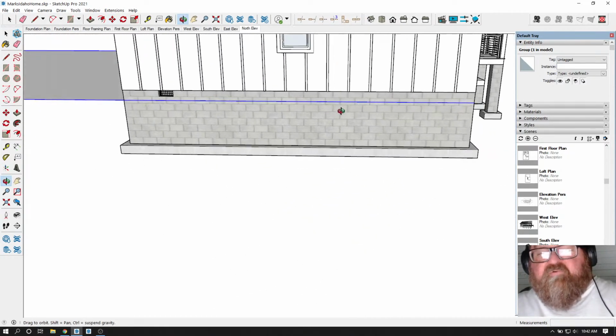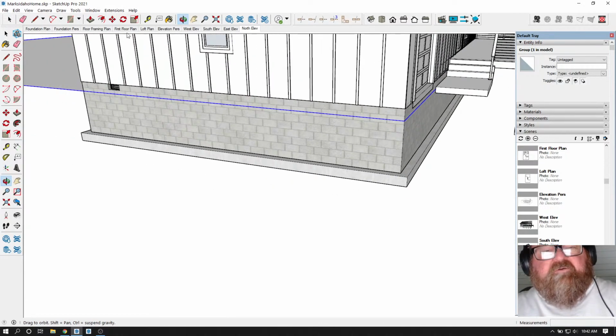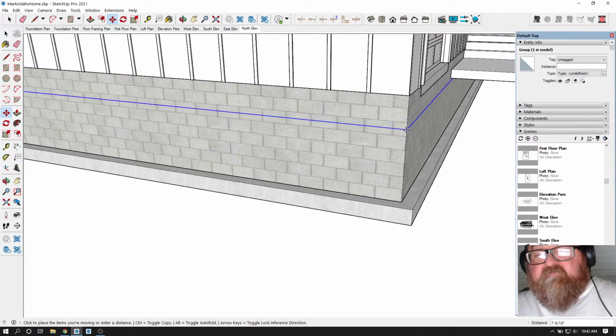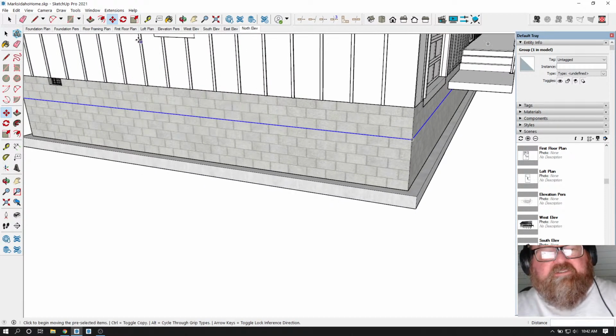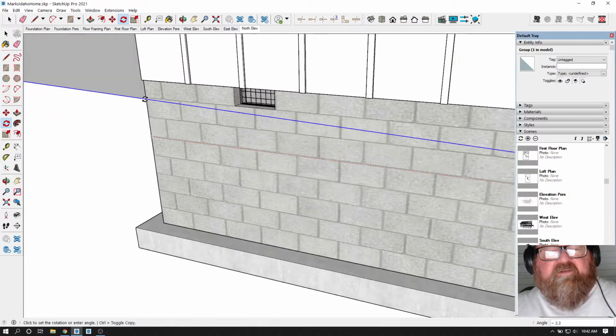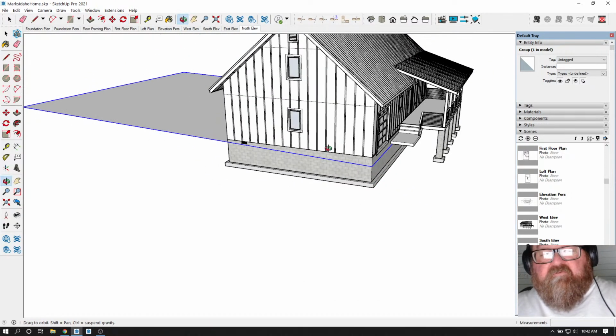But see, the problem I'm trying to stress to the owner is that I know that this slopes a little bit. I'm going to say it slopes at least 8 inches. So they may have a little bit of an issue when they start to do their garage. But I want at least a block sticking up out of the ground back here. See, because you don't want the earth above your foundation vent.